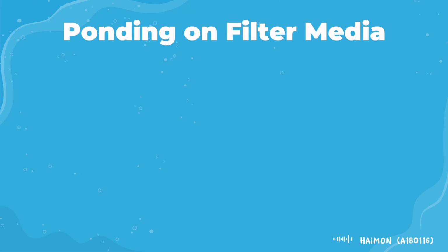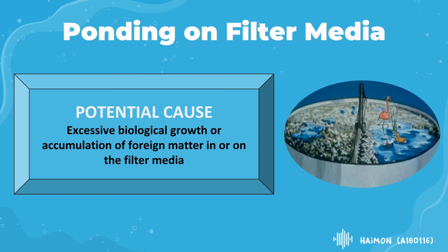Ponding on filter media is another disadvantage when it comes to the trickling filter. Ponding is when water can be seen standing on top of the trickling filters. The potential cause of this problem is excessive biological growth such as fungus or accumulation of foreign matter such as sediments in or on the filter media.